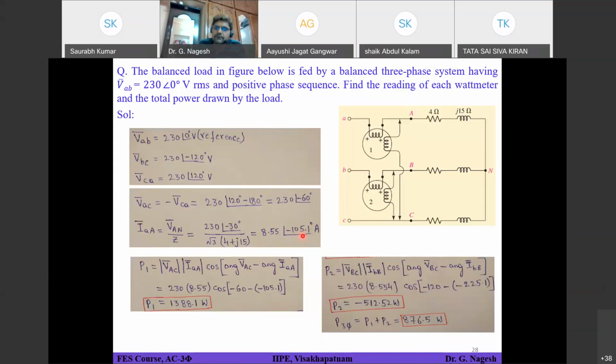Right. So that's it. You can calculate your power factor from your wattmeter readings, from the load side, or from your voltage and current values also, right? So all results will be the same, right? So I hope it is clear to everyone, this problem. You can cross check your answer whether it's right or wrong from your load parameters, from your current and their phase angles also.